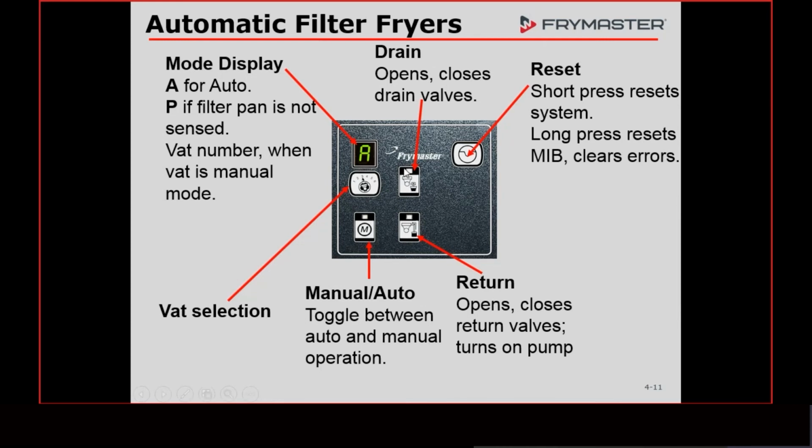So how do we check the actuator? We just swap this actuator for this actuator. It's on the same AIF board, or you may have a spare actuator that you just carry with you. If you do, you can just plug that in. If we swap these two around and now our problem goes here, meaning it stayed with the actuator, we've got a bad actuator. There's no more troubleshooting involved.